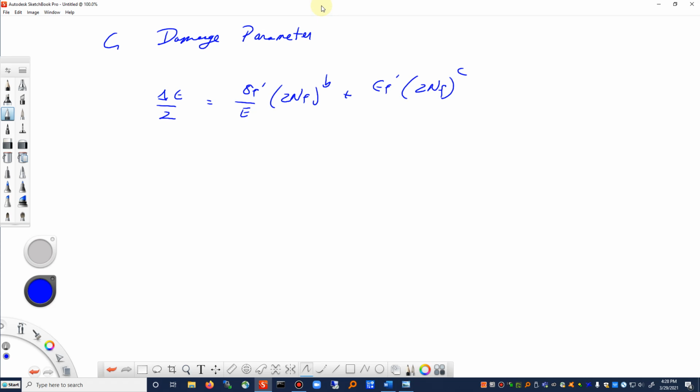They don't necessarily have to capture the exact mechanism. So we know that the damage in metals has to do with dislocations moving, and you can probably find a dislocation-based damage parameter. But the idea with the sigma f prime and the epsilon f prime, the b and the c, is that those are wrapped up inside those overall material constants. If we could look into the material and know the movement of every single atom, that might be great, but from a calculation and particularly from a design point of view, it's very hard to work with that level of detail when you're trying to make a product.